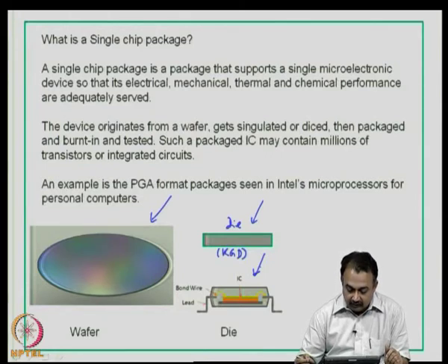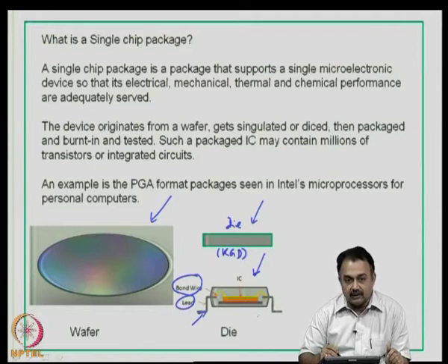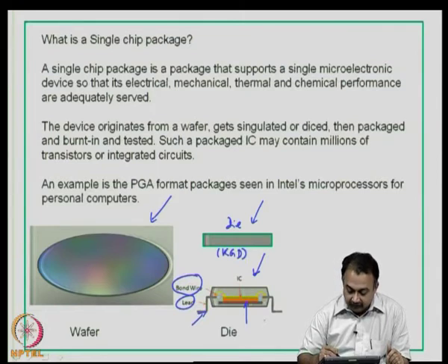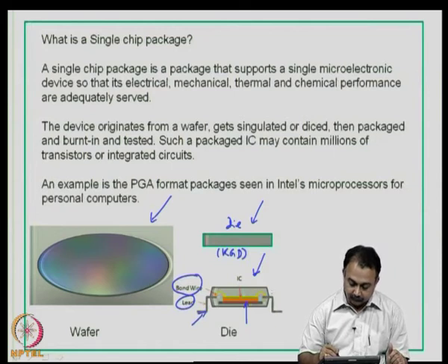In this particular picture, what you are seeing here is a wire bond, and then these are the lead frames, and then you can see the bare die at the center resting on a substrate. At this particular point, we are going to do a die bonding, and that is how it is resting on that particular base of the lead frame material. Then you can see the wire bond or the first level interconnection is attached to the lead frame, and then it is packaged